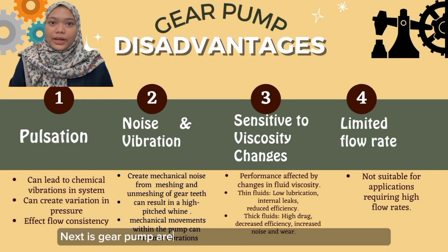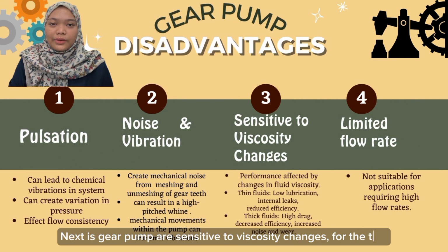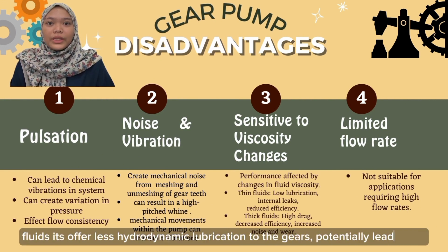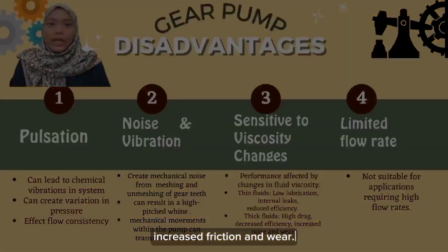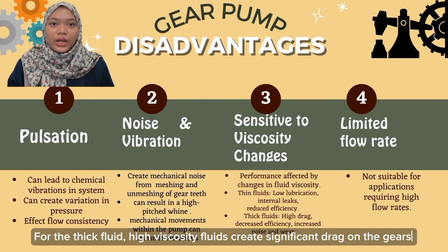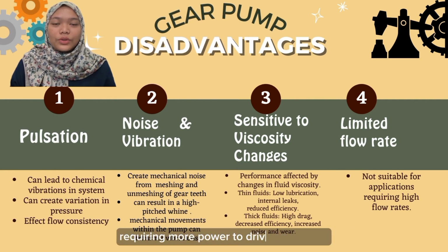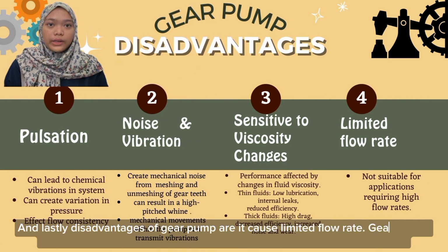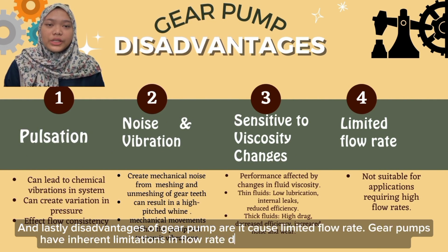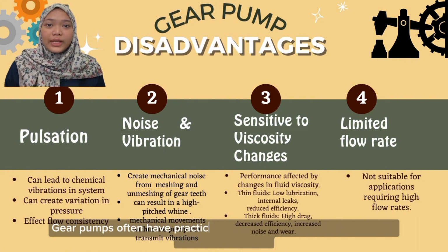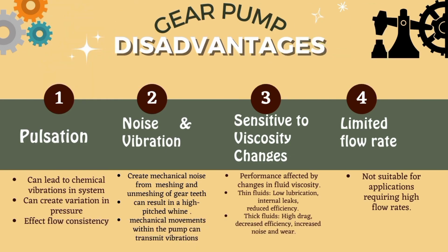Next, gear pumps are sensitive to viscosity changes. For thin fluids, it offers less hydrodynamic lubrication to the gears, potentially leading to increased friction and wear. For thick fluids, the high viscosity creates significant stress on the gears, requiring more power to drive the pump. And lastly, a disadvantage of gear pumps is that they cause limited flow rate. Gear pumps have inherent limitations in flow rate due to their size and configuration, where gear pumps often have practical or material limitations on their operating speeds.